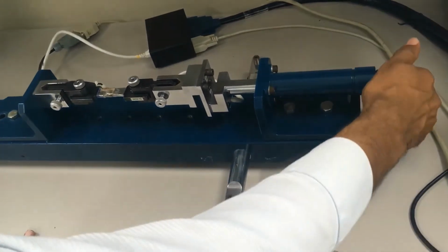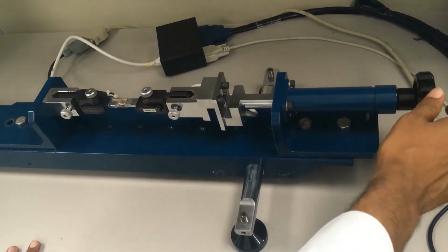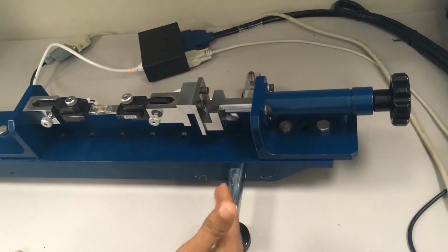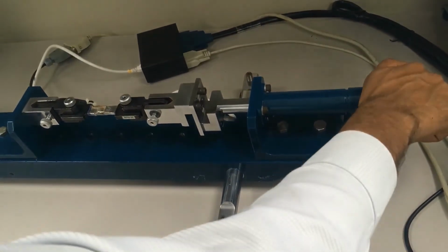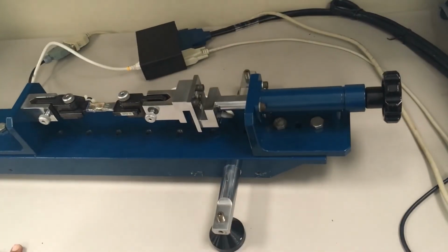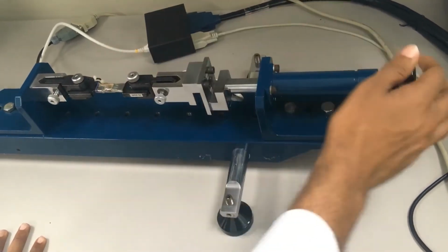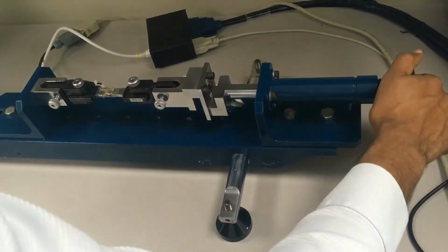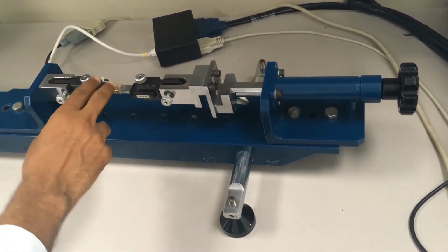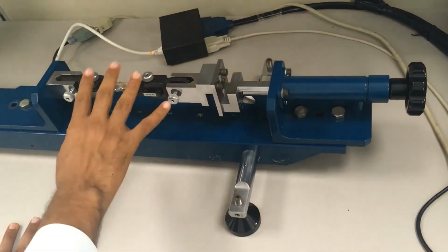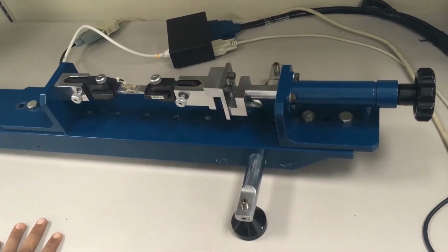So basically the experiment is that we want to change the forces maybe 5 or 6 times. So we'll apply a specific force, and in the computer, as you know, we have the indication of force. So in the computer we can see the measure that, for example, 10 Newton, we will apply some force and we stop until we see the 10 Newton, and then we can measure the stresses, strains, elongations, and everything. Again, we will change to another force, maybe 20 Newton, and we will read the data for the 20 Newton, and then again 30 Newton, and because of that we will have our curve of stresses, strains, and modulus of elasticity and everything.